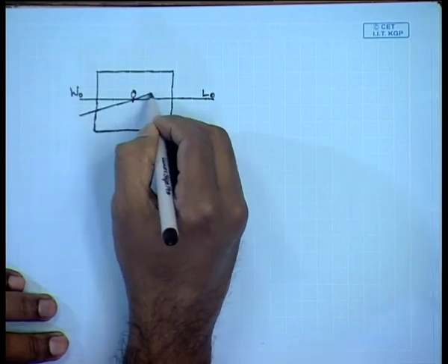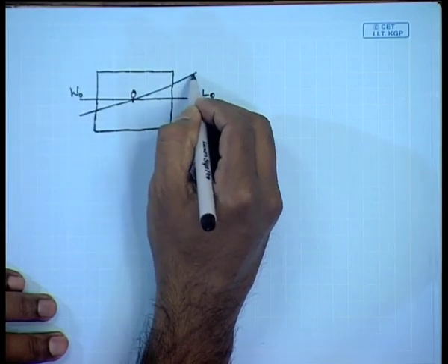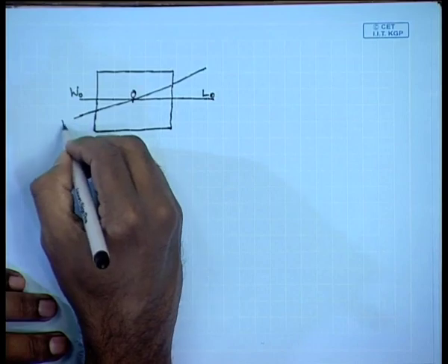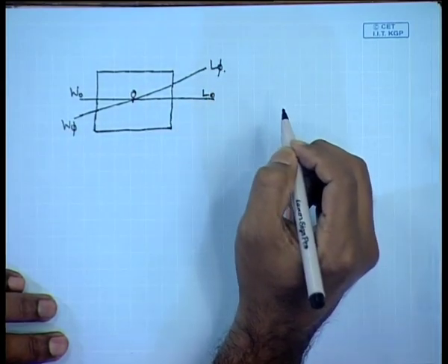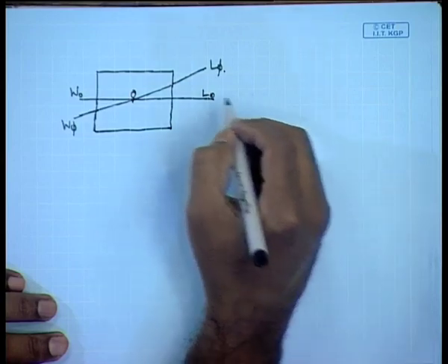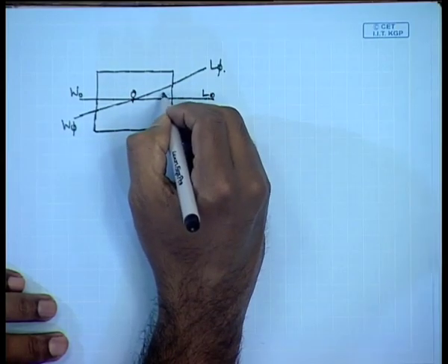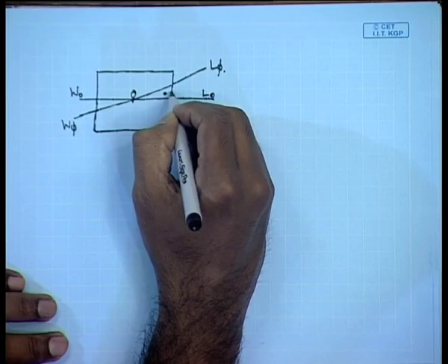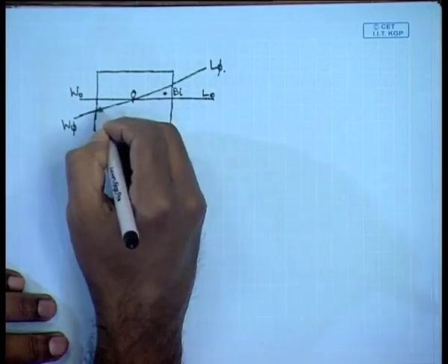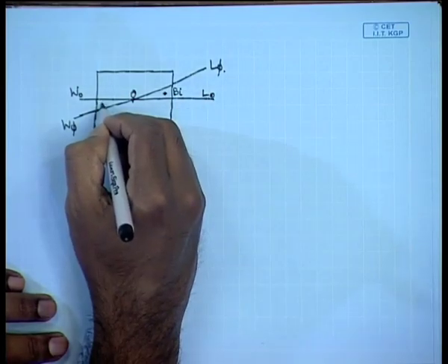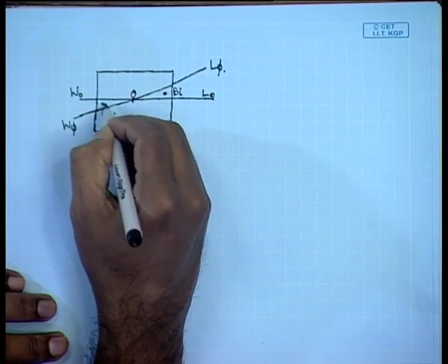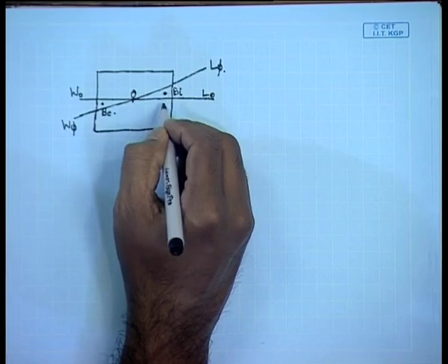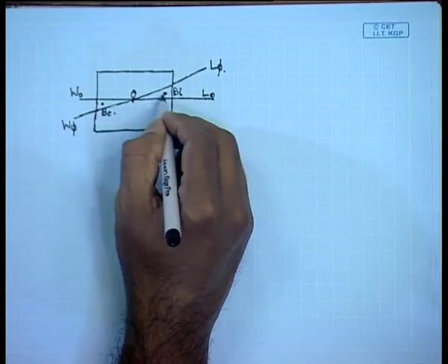And when it tilts, it becomes like this, W phi L phi. So here there is a region immersed somewhere here, the center of buoyancy of that region Bi, B immersed, and here is a region emerged, known as Be, the emerged region. So two regions.